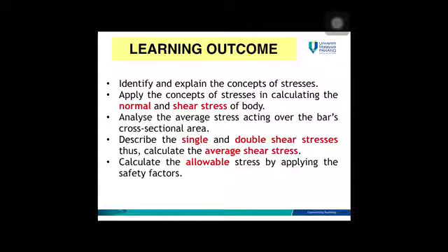From the learning outcome, you can see that you have two types of stress, which is normal stress and shear stress. Normal stress, you get it from normal force. Remember the normal force that you calculate in internal resultant loadings or internal resultant forces. This normal force you will convert it into stress. And then shear stress, as you will get it from shear force.